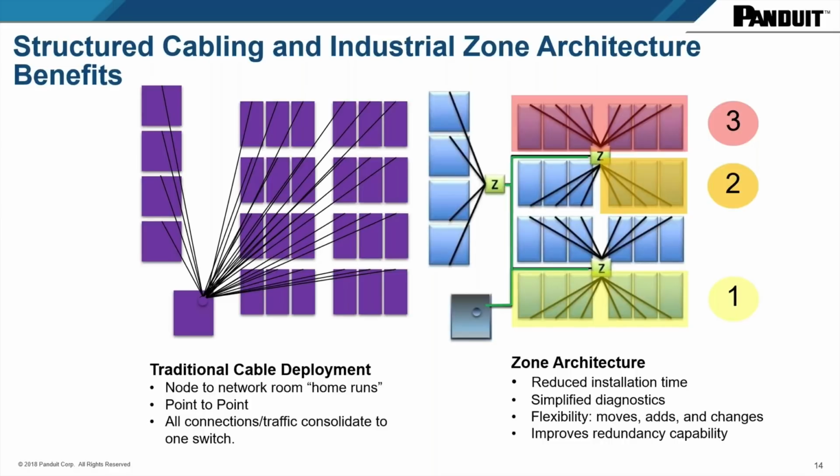That means that you would need to run 6 cables from area 3 back to the center in a star architecture, as you see on the left-hand side. And this type of cable will have to be a level 3 rated cable. So you have 1, 2, 3, 4, 5, 6 level 3 cables, rated in all of the MICE ratings, that have to be run the length to get to the central system.